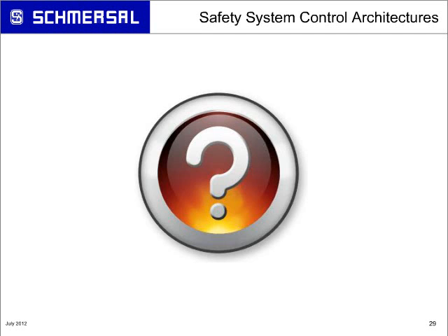Here's the first question. What about combining technologies such as mechanical with RFID or magnetic? It is possible to combine those technologies together where the electronic switches do their own cross-short recognition, and putting the mechanical switches in series with those, you get into a gray area of what you really achieve, whether it's control category 3 or control category 4.